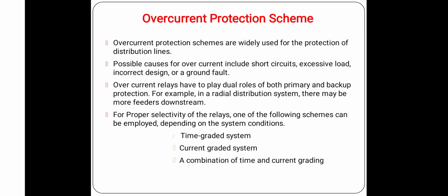So the selective protection principle affects the operating speed of this protection scheme, which has a significant impact on the harm caused by short circuits. Basically, the faster the protection operates, the smaller the resulting hazards, damage, and thermal stress will be. Further, the duration of the voltage dip caused by the short circuit fault will be shorter the faster the protection operates.